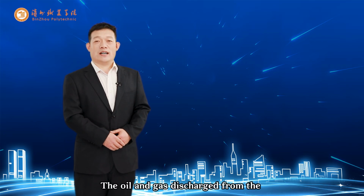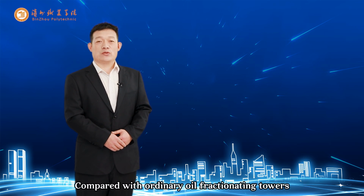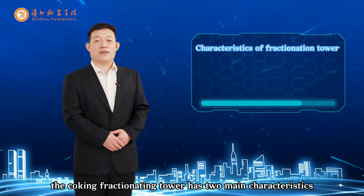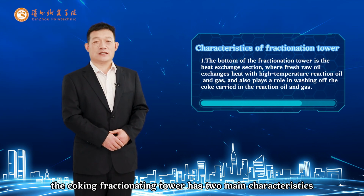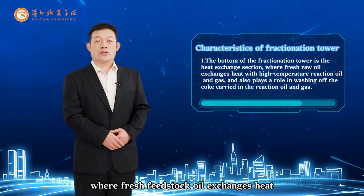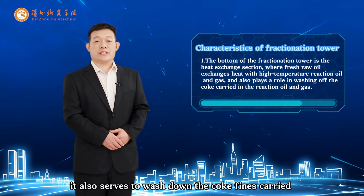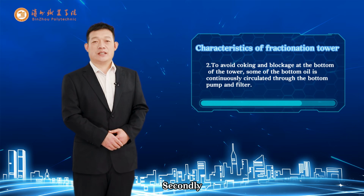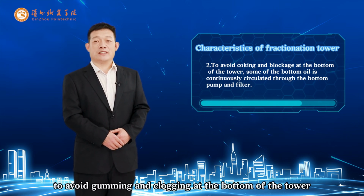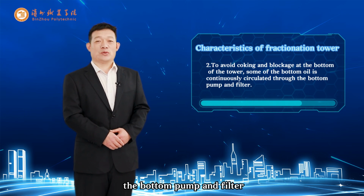The oil and gas discharged from the coking drum enter the fractionating tower for fractionation. Compared with ordinary oil fractionating towers, the coking fractionating tower has two main characteristics. Firstly, the bottom of the fractionating tower is a heat exchange section, where fresh feedstock oil exchanges heat with high-temperature reaction oil and gas again. Meanwhile, it also serves to wash down the coke fines carried in the reaction oil and gas. Secondly, to avoid gumming and clogging at the bottom of the tower, part of the bottom oil is continuously circulated through the bottom pump and filter.